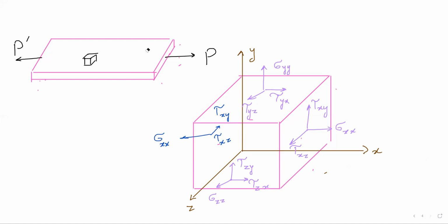But this is actually our next comment. I'm happy that we are doing it, but I will explain the reasons. What is the reason? Newton's first law, right? Because in the static case, there is an action and reaction. Exactly. Summation of moments has to be equal to 0. So within the next 3 minutes, I will explain why the shear stress on this face is upward, this one has to be downward, anti-clockwise. Then on these 2 surfaces, it has to be clockwise. So you have to give me a few minutes. But right now, I want everyone to be on the same page in terms of naming them.